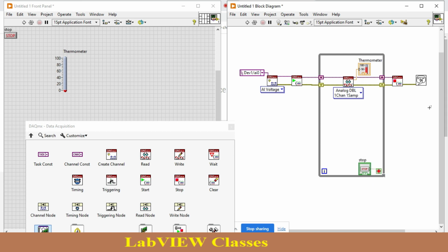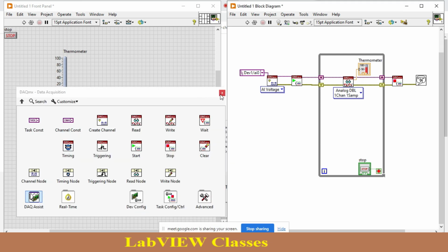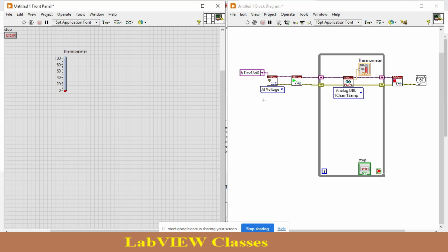The temperature data is in the form of voltage, because for every device, when we deal with temperature, flow, or pressure, and we want to read this signal, it is in the form of voltage or current, and most of the time it is in the form of voltage. Maybe it is clearer to you as you are working on different hardware devices. So right now, as you see, my temperature is there when the thermocouple is connected to AI0.